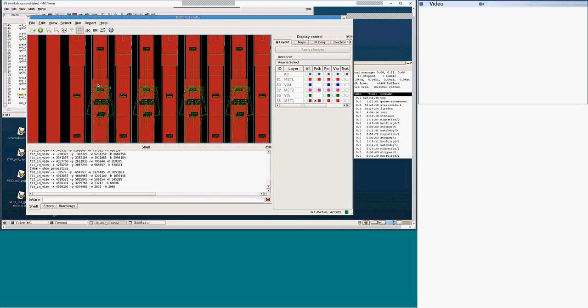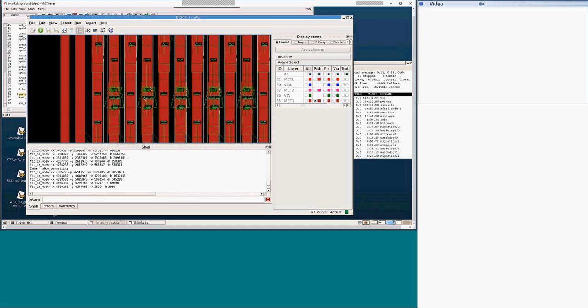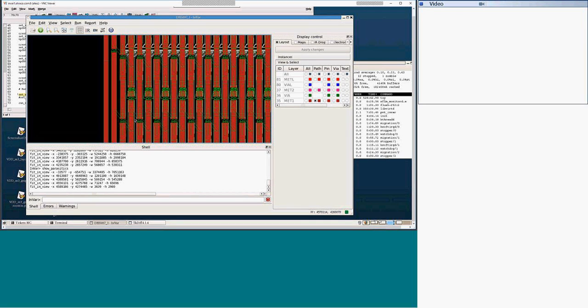Contacts. Yes. These guys with trapezoid shape are probably representing contacts. So you see, we do not show contacts to poly or contacts to diffusion, but these are still extracted as metal 1 resistors. So they actually go to diffusion, I guess, at these points. I just did not read metal to diffusion contacts, and I cannot display them here. But I believe you are right. This is the point where you have contacts to diffusion.